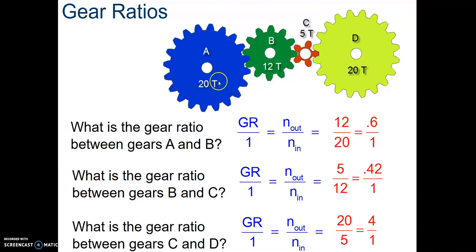So just taking a look, big to small, small to big. We are decreasing size, so we'd increase speed. Increase size, so we'll decrease speed there. Because if we go 5 here, we're only going 5 here, so one revolution here is only about a quarter of what's there.